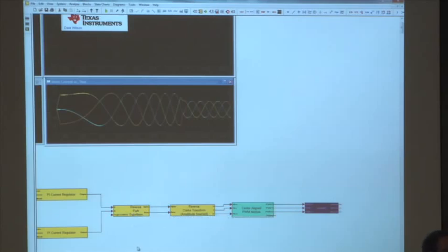And if you do that enough times, you're going to have a big mess here. It'll look like a hairball of wires running everywhere. I prefer to do it with assigning variables. So go up to the toolbar, and you're going to see this block right here. It's a red block called VAR. It's got a red VAR on it.